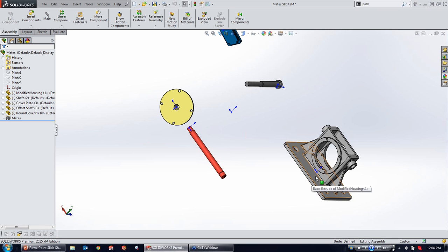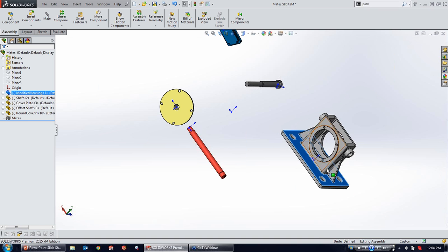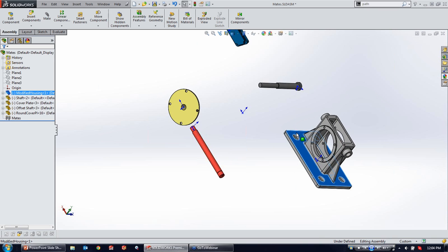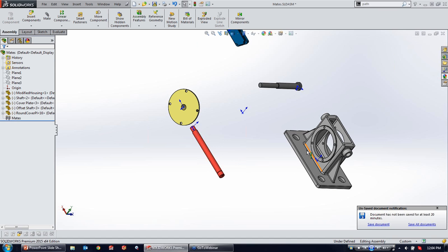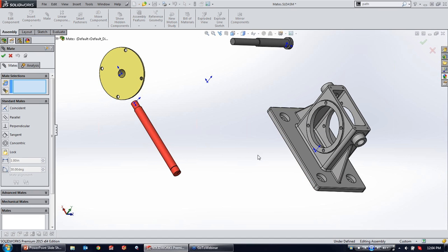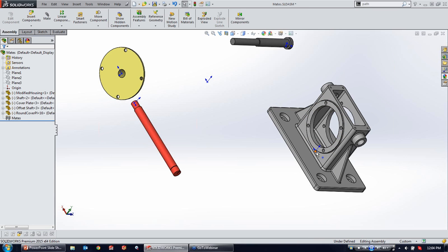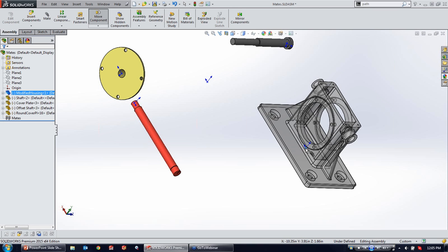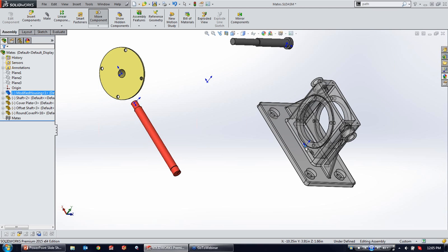Now, whenever I go into an assembly, typically your first part is fixed, but it doesn't always mean that it's fixed on an assembly. So what I did here was float my first part in my assembly. And instead of coming through and saying, all right, I want this fixed on the origin, first I'm going to have to go to my mates, and I want it on my front plane and match it here, and then I want my right plane and match it here. Instead of giving that 3 separate mates, what I can do is select my origin here and hold down my Alt key with that selected. So the Alt key is your trigger for your smart mate.